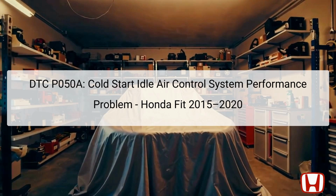The Diagnostic Trouble Code, DTC P050A, indicates a cold start idle air control system performance problem in the Honda Fit from 2015 to 2020. This code is related to the Powertrain Control Module, PCM, which manages various engine functions, including idle air control. When the PCM detects that the idle air control system is not functioning within the expected parameters,